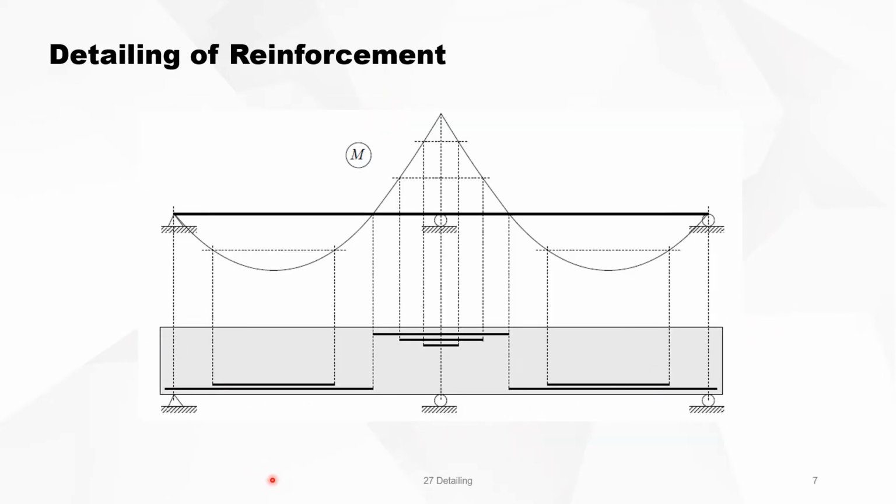If you have a continuous beam, you can see easily for the bending moment in the field, you have the first layer of the first length of bending reinforcement, and then a second layer covering the maximum bending moment. The first layer is covering the bending moment until here, until this line. The same happens with the bending moments on top. So you can cut off your reinforcement and use only the reinforcement where really needed. So you save some reinforcement.